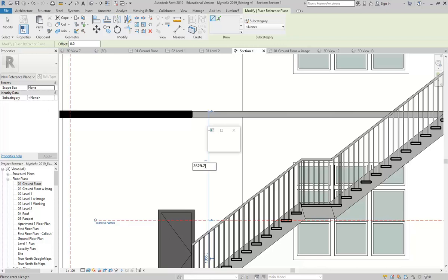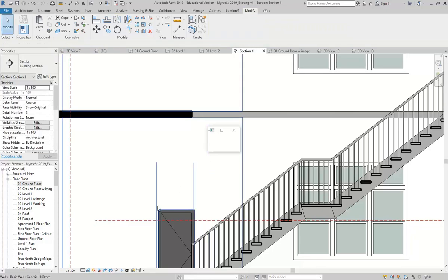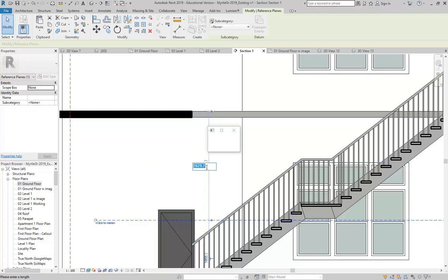Sorry? Did you say, you're not on the right track, that's the right. Well, it's not even that high. So normally it's 2100 is the absolute minimum ceiling height. 2400, you're right, is for most habitable spaces, but you can go to 2100 for bathrooms and kitchens and things. And that's always good to remember. If you need to go down to 2100, that's sometimes necessary. But there's a special provision for stairs. You can actually go down to 2000. Yeah, just for stairs. And so I'll make this 2000.